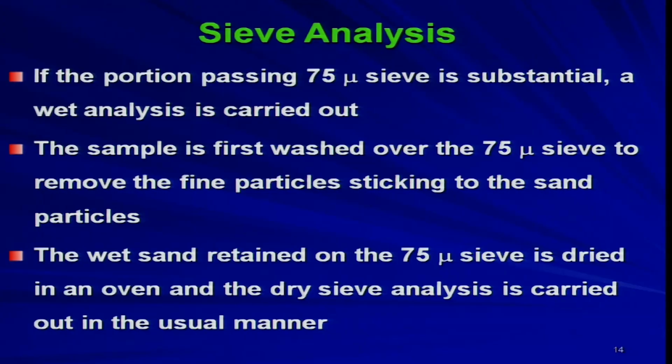So, that is why it is known as wet analysis, because you first wash the sample and then you take the sample retained on the 75 micron sieve, make it oven dried, and then take that sample to do the regular sieve analysis.